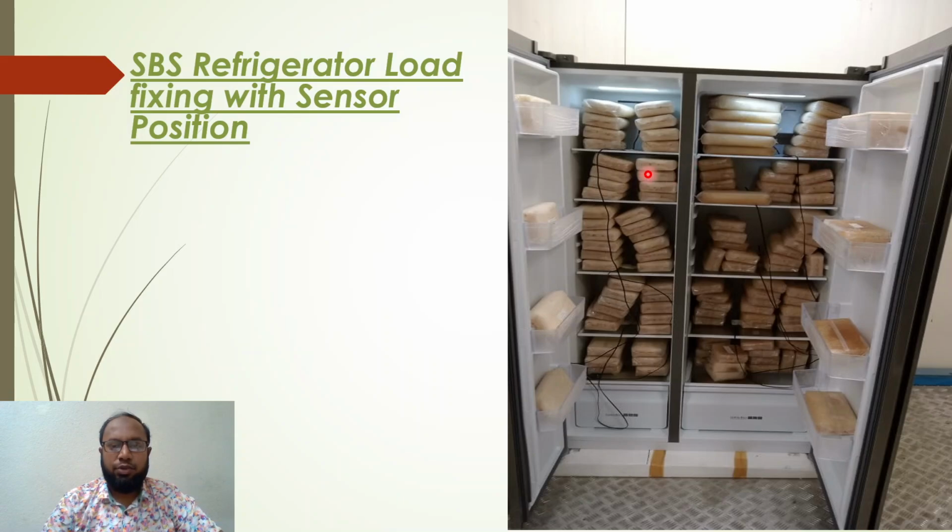After we put the load in the refrigerator and start the test, it runs continuously to reach the inside temperature. The compressor is always running to achieve the temperature. After achieving the temperature, the compressor does the cycle as per the general rule. As we look at the temperature curve of this refrigerator, we can understand how many hours later it will cycle, or how many hours later it achieves the temperature. We can see this in the temperature curve.